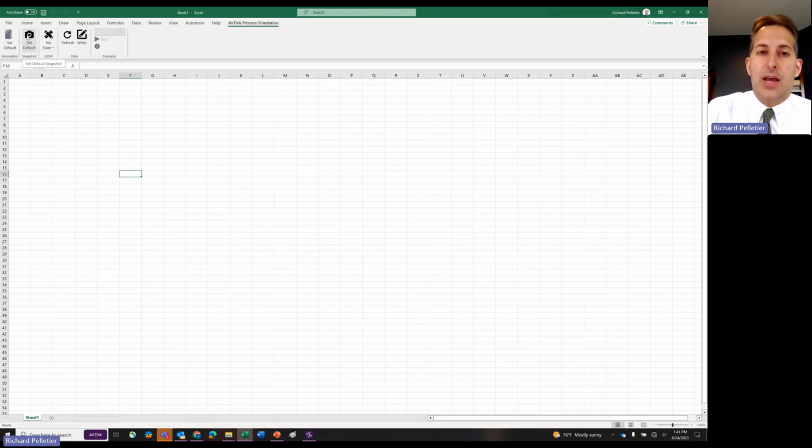And that's okay. You don't have to set a default for all of these. If you don't set a default, you either need to provide the value yourself, or in the case of snapshots or units of measure, it's going to default to whatever is currently being utilized within the simulation. So I don't have to do anything here. For the units of measure, I can pick a specific slate. I just need to make sure that whatever I pick has the units of measure for the different properties that I'm interested in. Now notice this slate selection is only for slates that are in my repository for my units of measure.